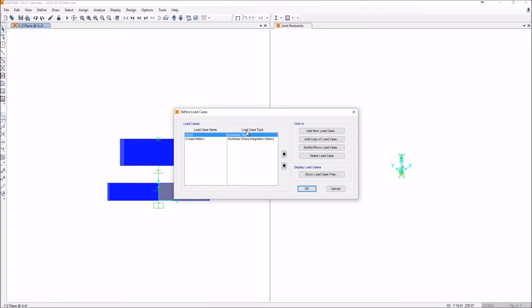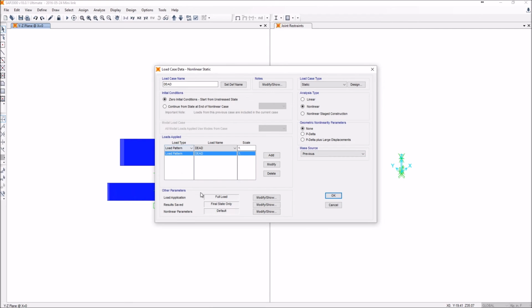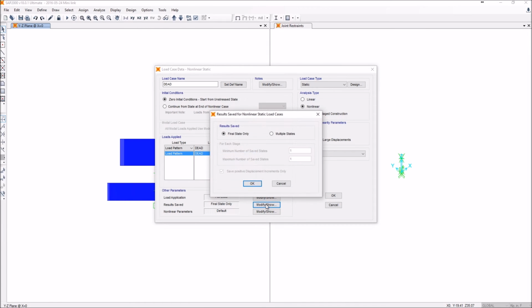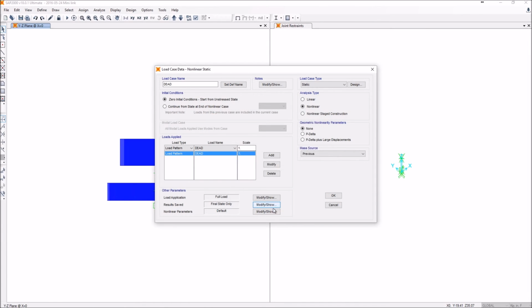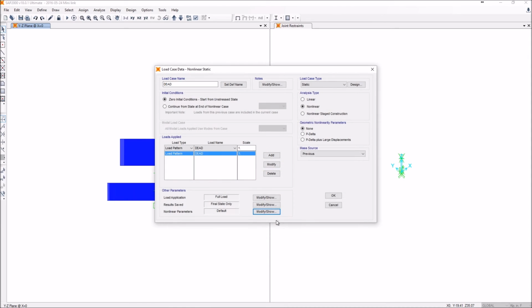So we go to the load cases. First I have the dead load, and here I show all of the properties I selected for it. It's a static case with the nonlinear effect selected, just in case I choose any nonlinear properties later on, and it shows the degrees of freedom. I don't know if you noticed, the U3 direction was selected, and I left everything else standard.